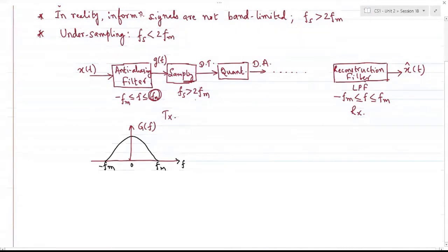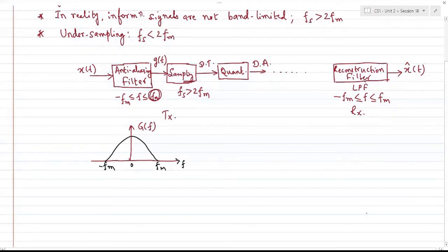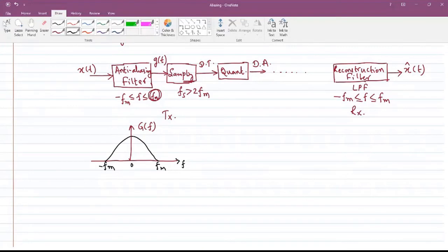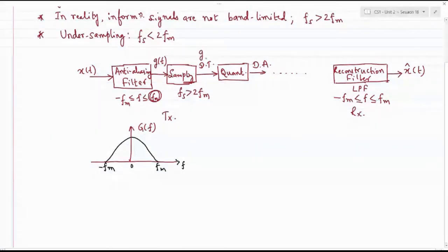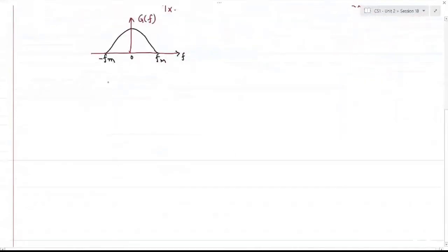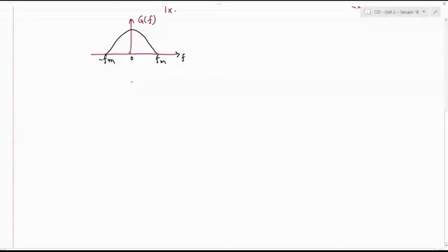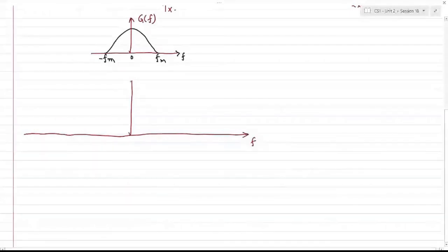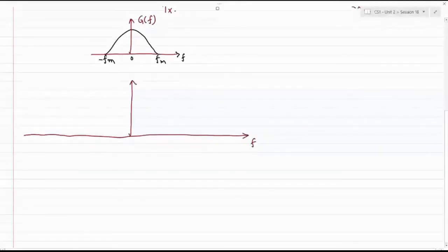Then you try to sample this at a rate much higher than the Nyquist rate itself. If I call the output of this sampling block g delta of t, it's a sampled version of g of t. If I try to plot that signal, it's just a replica of all these, as you have seen through the several types of sampling. So this will give me replicas of this.